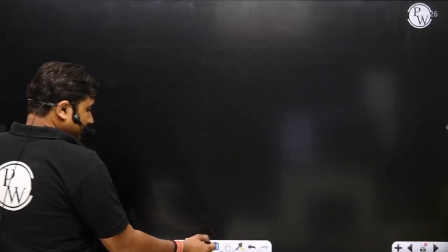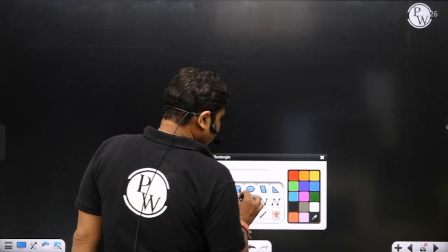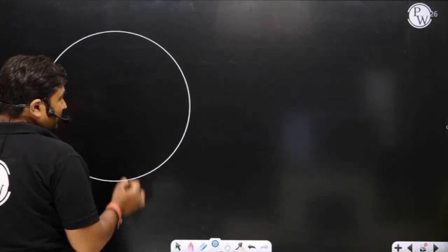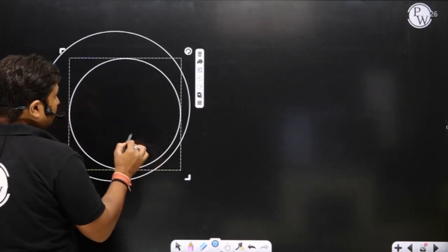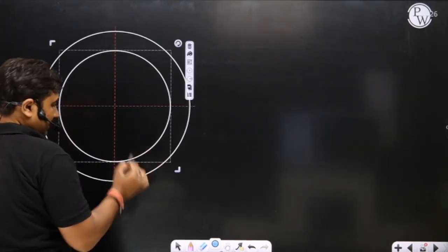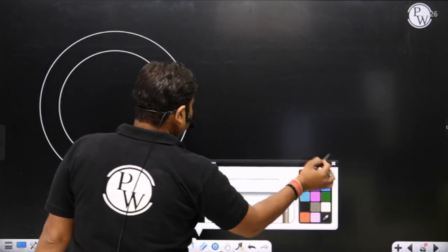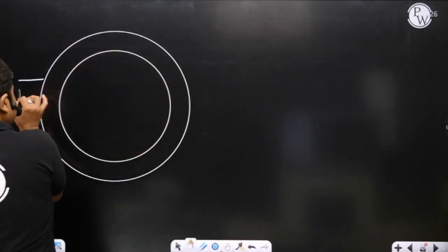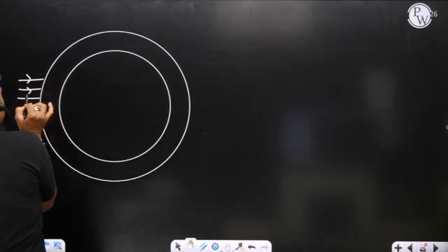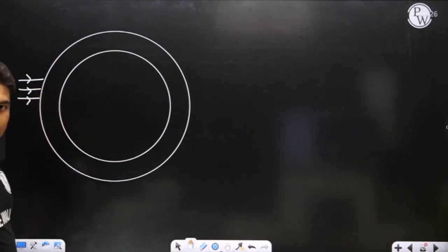So please see, I am going from the initial part again. Suppose we have a stator here. This is a 3-phase stator displaced in space by 120 degrees, and this stator is being supplied by 3-phase current displaced in time by 120 degrees.